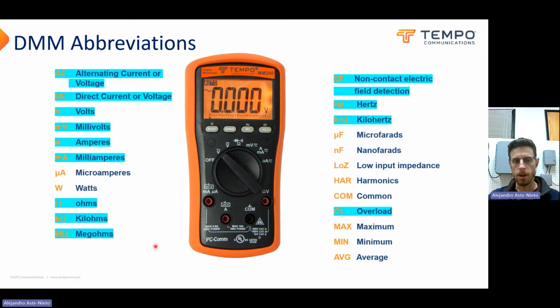But that said, there's a certain threshold above which this is just not going to be able to measure. If we're dealing with over 600 volts, these multimeters are not going to be prepared for taking a measurement there. They will say OL, they're not rated to be handling that kind of voltage. So if you see OL and you're measuring voltage or current, that's dangerous and or damaging.